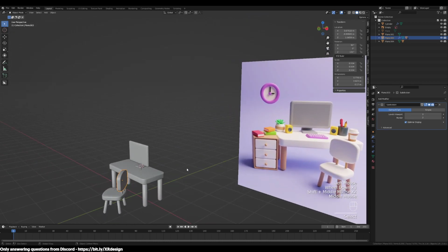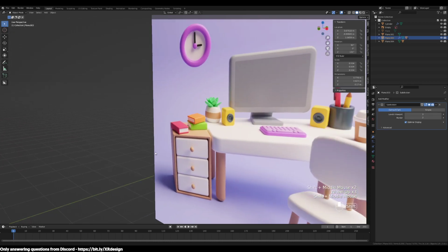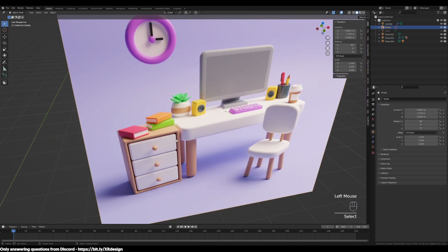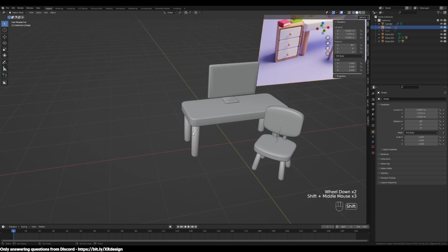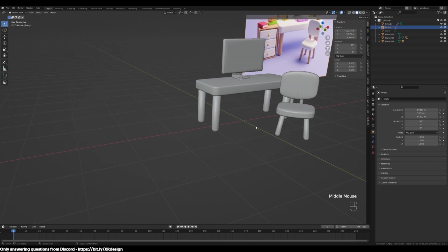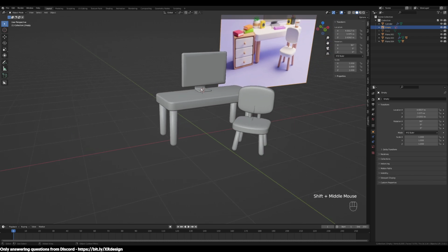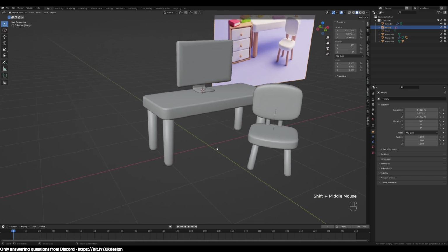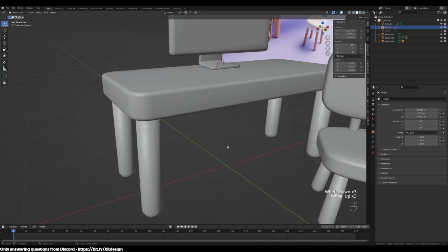Okay, so with that done, let's go with the drawer here. So I'm just gonna go back down, and I want to spawn the object so that it's sitting on this red line, so I can just move it over. Let's reset the 3D cursor to its origin point of the viewport. You can do that by either hitting Shift C, and that should zoom out and reset the cursor, or just do Shift S and cursor to world origin, and that should just bring it down here.